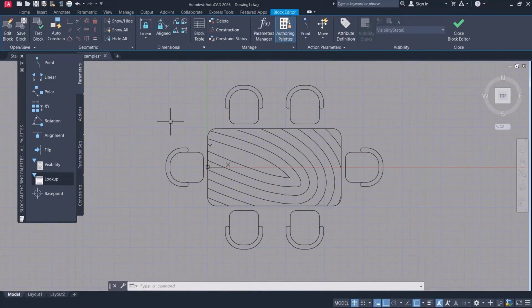So, as you can see, to create a dynamic block, we need to assign a set of parameters and actions. A parameter, as its name suggests, simply assigns a parameter, a label, or a position to an object. Then, for that object to have the necessary functionality, to be able to perform an operation, like that door we were able to move, rotate it 30 or 90 degrees, or make it bigger or smaller, or turn it into a left or right opening, these all require actions to be assigned to them, so parameters without actions are meaningless. Now let's go through them one by one.